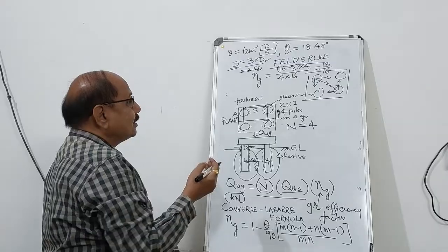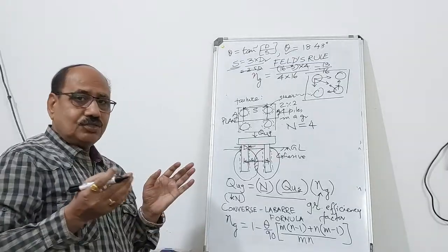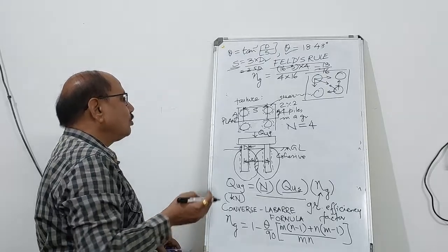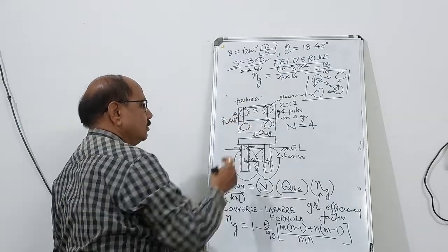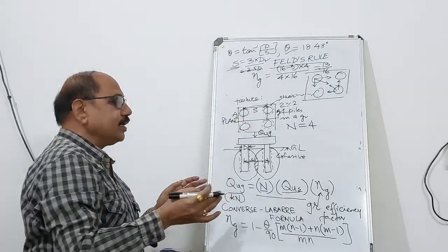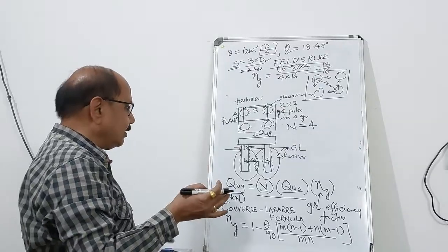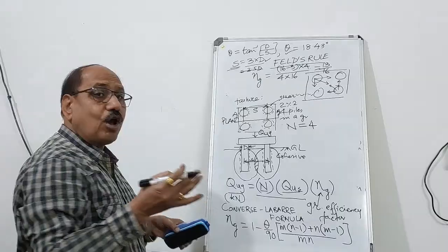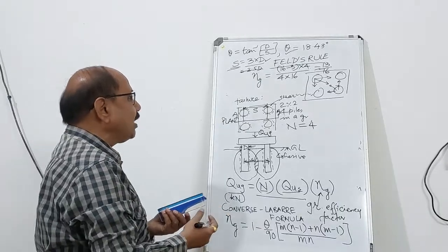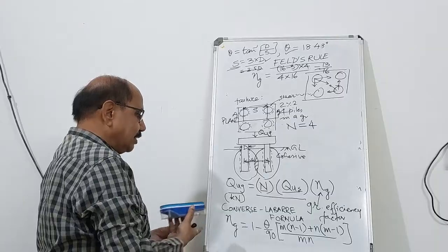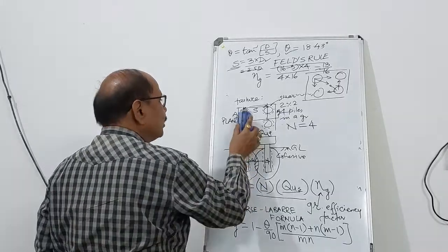Now the pile group can act as one unit, one monolithic unit. It is not going to fail one by one. On the contrary, it will act as one monolithic unit and it will fail. What do you mean? That is called block shear failure. So what do you mean by block or group shear failure? And based on that, the QUG you will have to calculate.